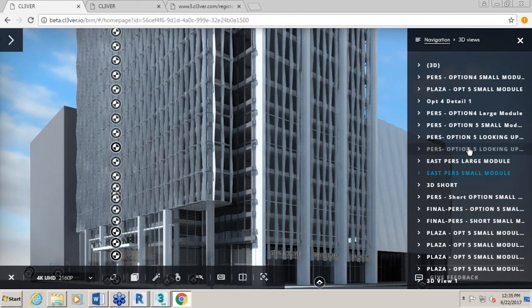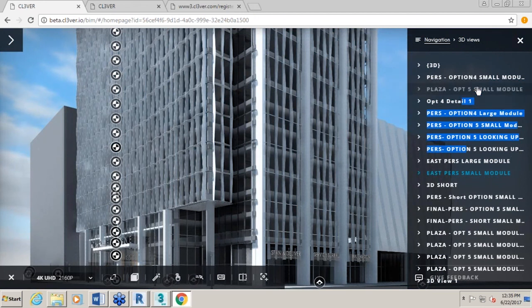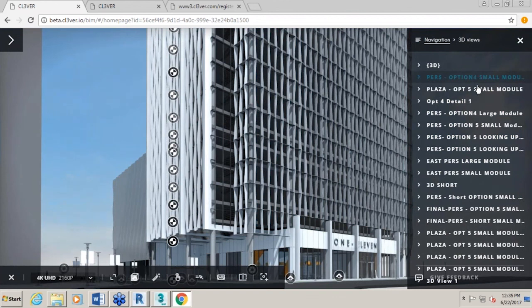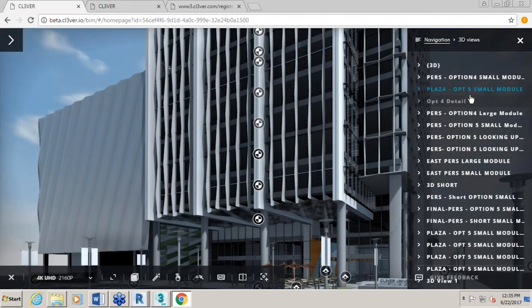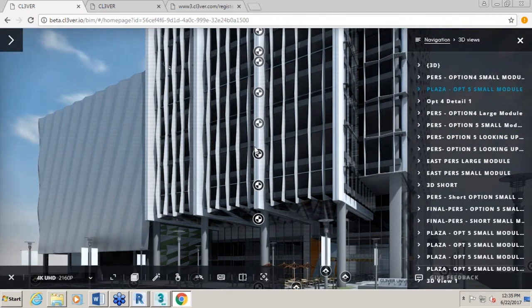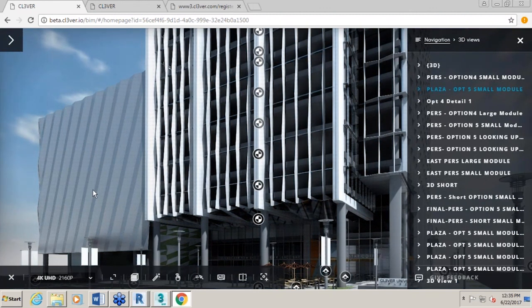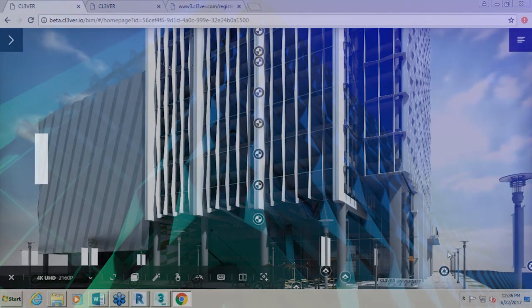Yeah, just to clear the workflow, you download the plugin from the workspace, you install the plugins automatically into Max or Revit. Right now we support versions 2016 and 17. And you import the scene from Max or Revit, and it opens a window locally. If you like the scene, you just upload it to your workspace, which is in the cloud, where you can access the scenes and share them with your colleagues or clients.